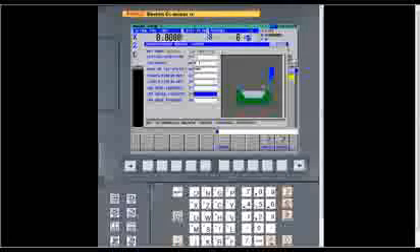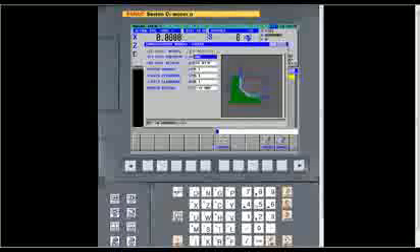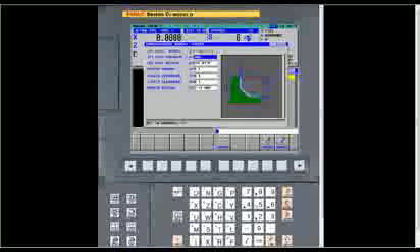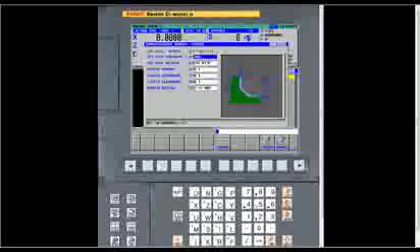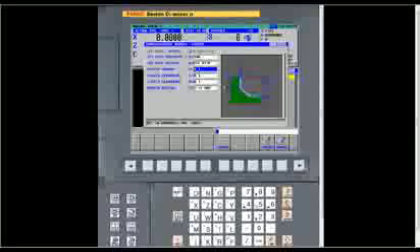Then feed rate, your straight feed rate. Then the angled feed rate, if you're doing a relief, you can slow that down. And then when it comes out of a relief. Then you have detail data. The first one is first feed rate override. That's for like on a lathe, if you had something chucked up in hard jaws where it was running out, you'd have the capability of slowing down that first pass, only the first pass. Then after that, it'll go back to your commanded feed rate. The cut rise method, that's for when you're turning over to a shoulder, when it feeds up to go back to the next move. You always want to use cut there, because otherwise it's going to leave big steps on a shoulder. And the rest are all just clearance moves, and then your approach motion like before.